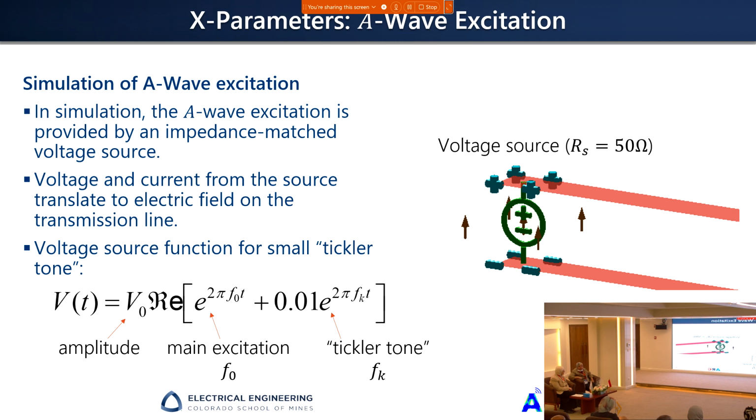Actually, no, this is the input voltage here, and you can see the input voltage has a fundamental frequency, and we are putting some small signal into the system as well, 0.01 relative to 1 here, to basically excite the small signal and the large signal into the nonlinear device itself, which is the diode here.